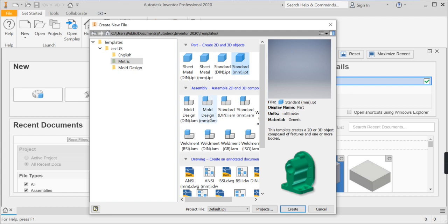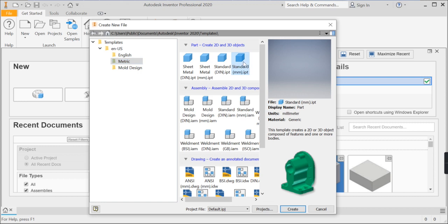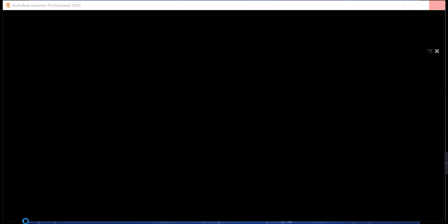So you must choose these as the units are in millimeters. If I was to, for instance, click another different one, you can see the units are still in millimeters, but they are making different parts. So we need to be really specific with this and choose the correct file each time. If you were just to click the original one, it's automatically in inches. So again, can't exaggerate enough, must choose IPT. Give your file a second to load, it tells you down the bottom it is loading.